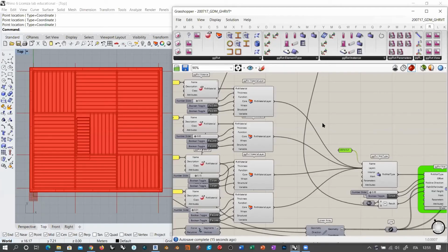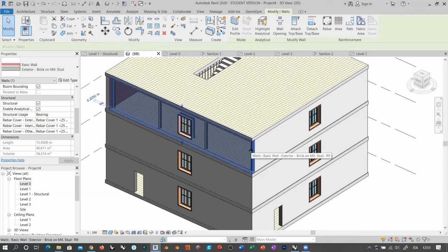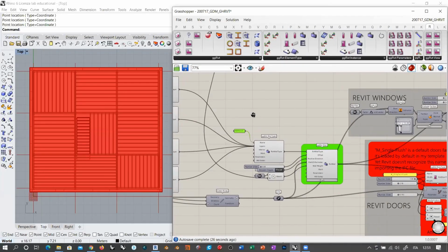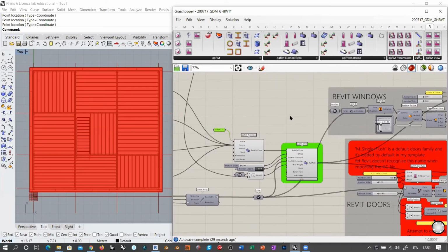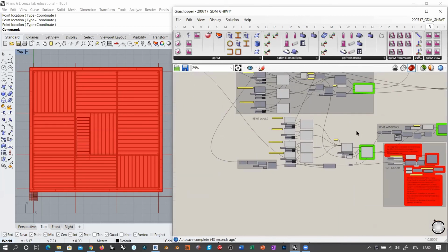Okay. Remember that these walls are actually recognized by object ID during the import process. So basically, as I didn't change the path or perimeter, I just changed the wall type, the object ID should still be the same. Okay, so this is the purpose of this part of this session.